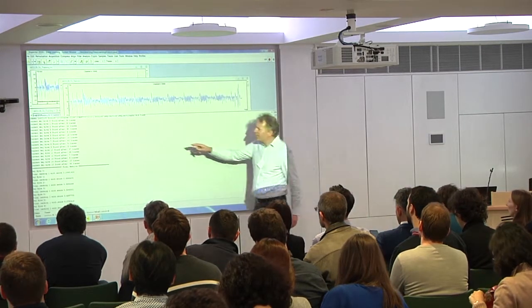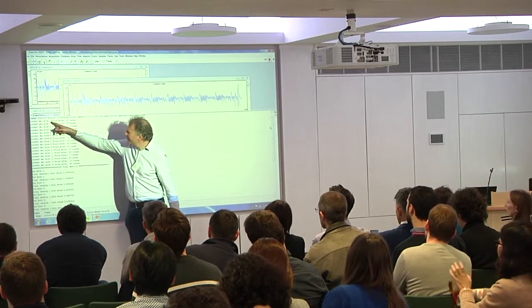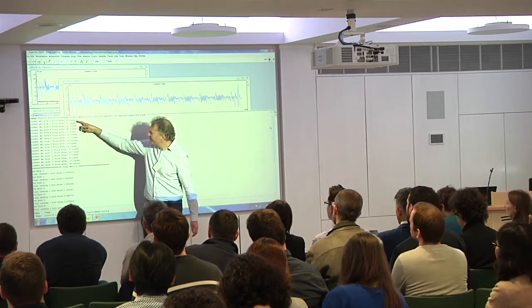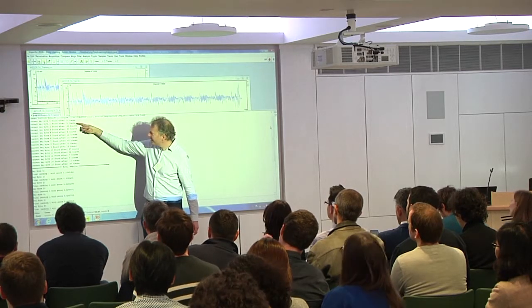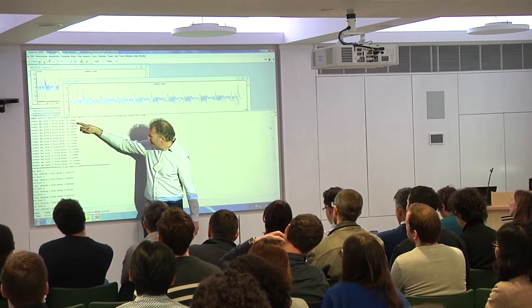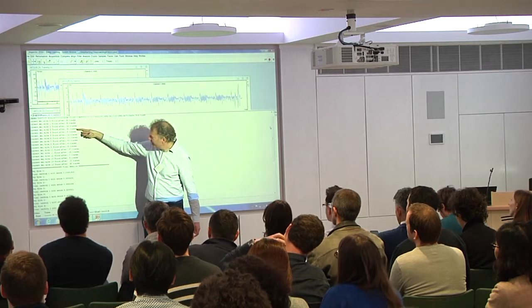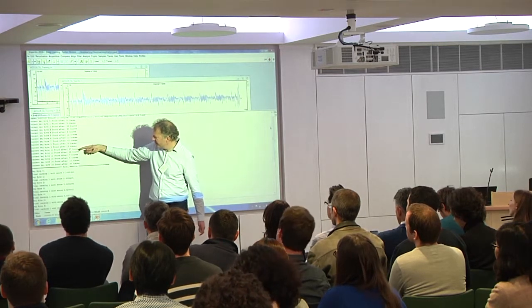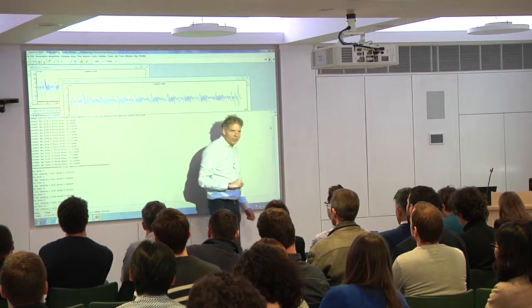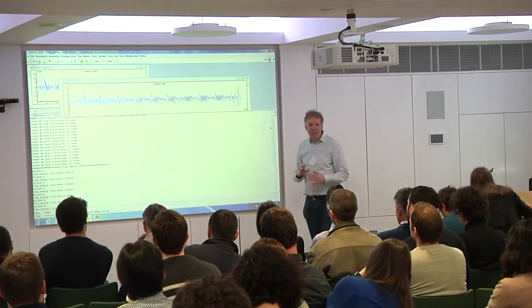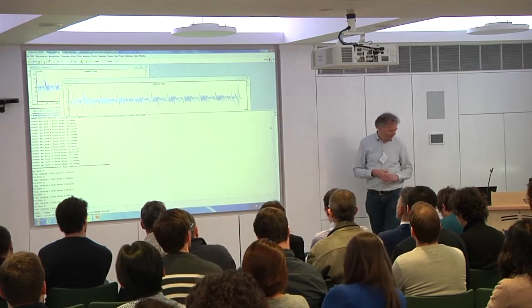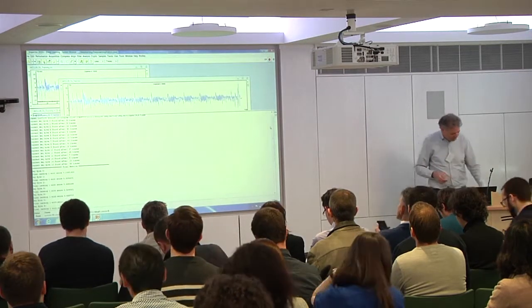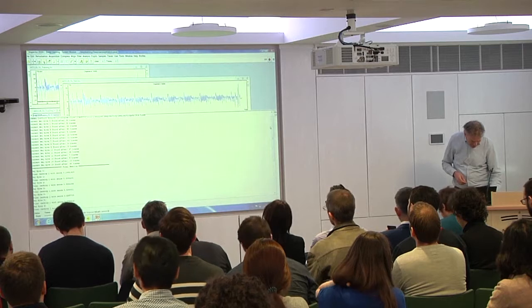For those of you who can read it, for key byte 0, the correct key byte was found after 9 traces. For key byte 1, the correct value was found after 8 traces. There's a few that need a bit more. Here there's 60, there's 43, 37, but it's all very modest compared to the training sets where we used 5,000 traces. So this sort of demonstrates the capability of deep learning.